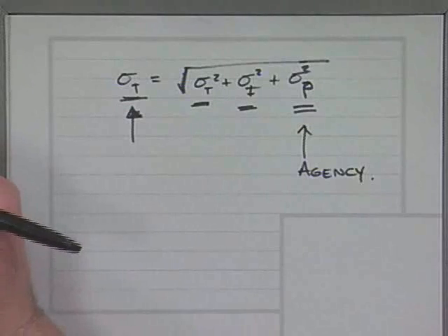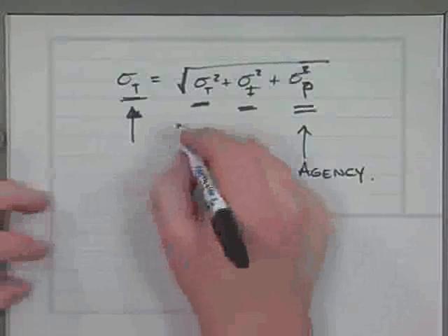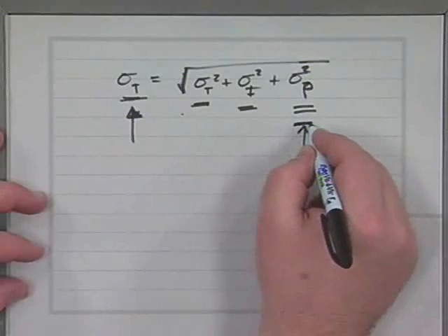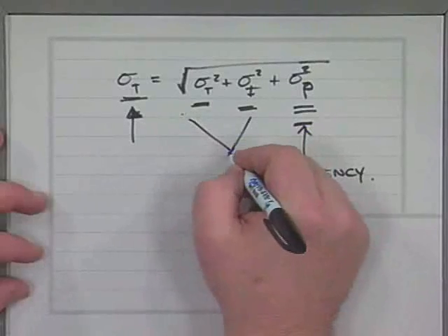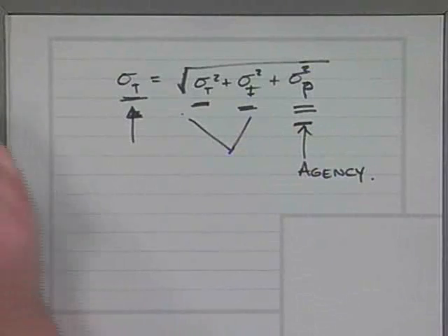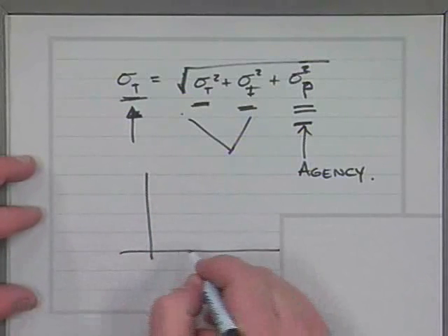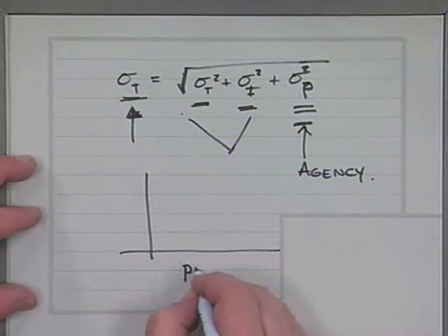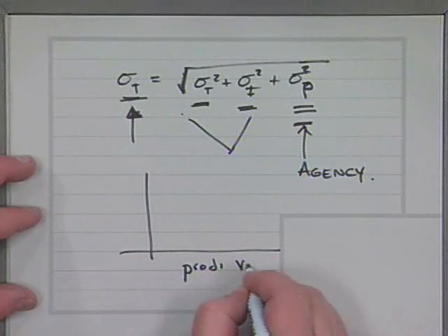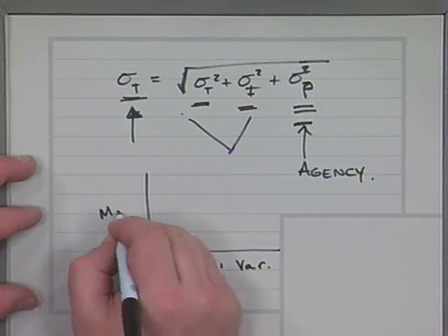What most agencies want to control is the production variability. What contractors need to be very careful of is that they don't set the variation so small that you can't reliably test it. If you started to plot on any particular axes here, you could plot production variability versus measured variability.